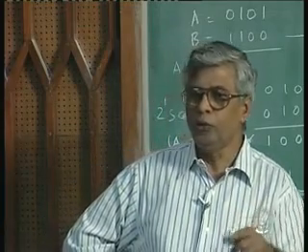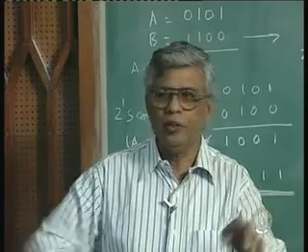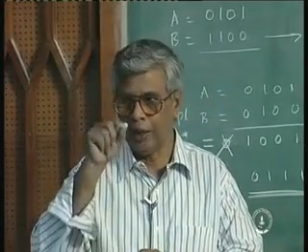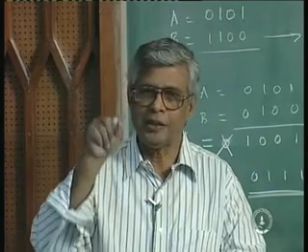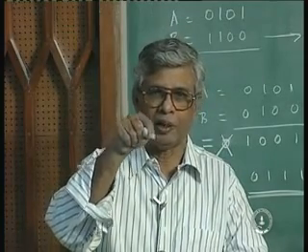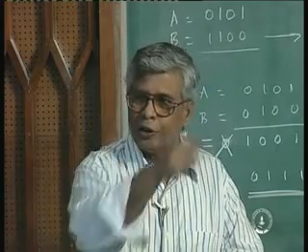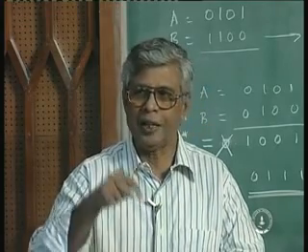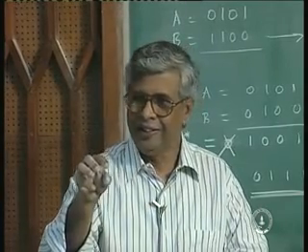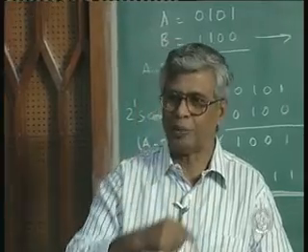So if you want to give a negative number input to the computer, you don't give a number and punch in this negative sign in the calculator. Of course you type that, but the minus sign of the number does not get stored. If you punch the plus-minus key in the calculator, a minus does not go and get stored. The number you had written earlier has to be converted to 2's complement and stored with a 1 as the MSB.